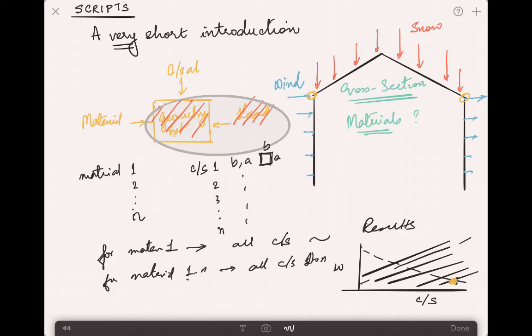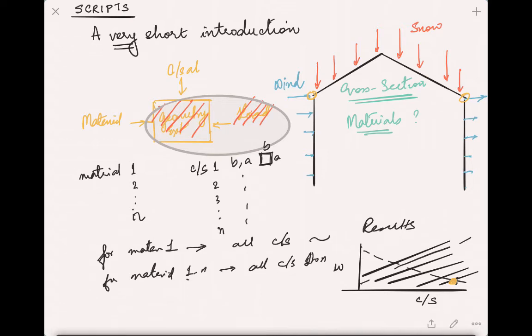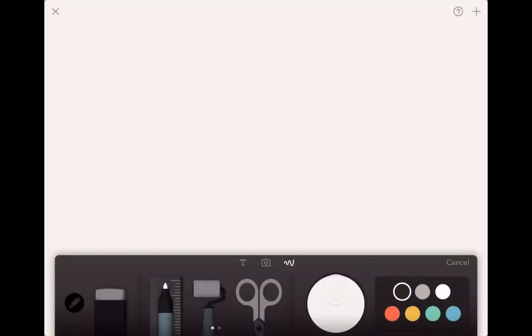So in all the different programs, you will have it differently. So let's first just look at Abaqus. In Abaqus, there are different options. If you're using the commercial version, then what you do is you set up your replay file. So the moment you launch your Abaqus module and you start putting something into it, you create a part, you put boundary conditions, etc., and you save it. In your work folder, you will see a .rpy, which is a .replay file.